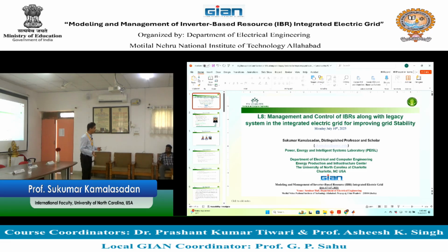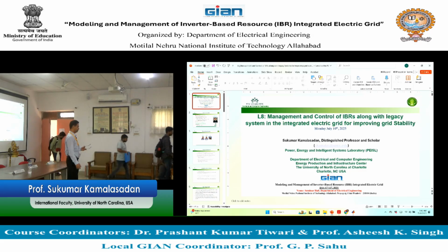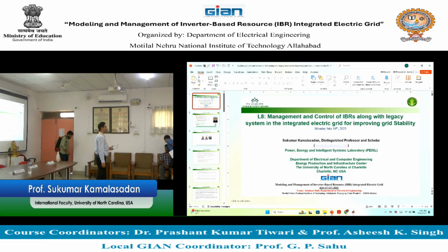What are the set points? Set points can be active power. Set points can be the reactive power if needed to go to the inverter and operate the inverter. Mainly the active power requirement can be derived from power flow. If you use an optimal power flow, you will get the active power considering the cost, whatever the cost objective. So that's what we did first.